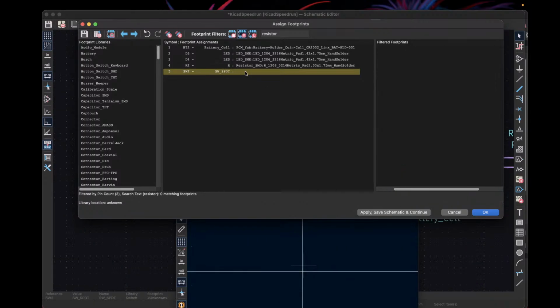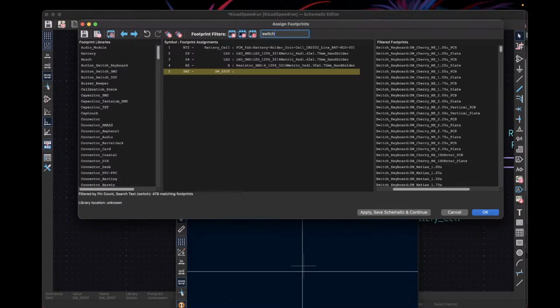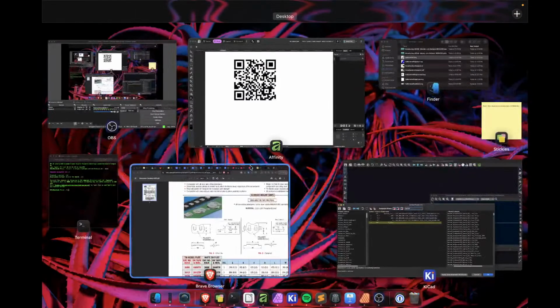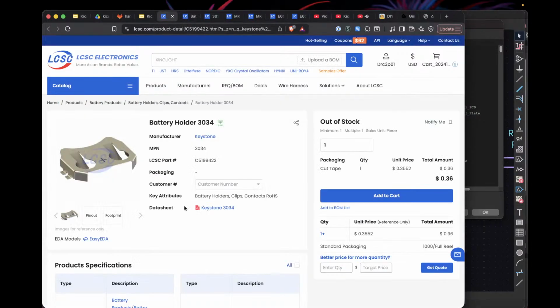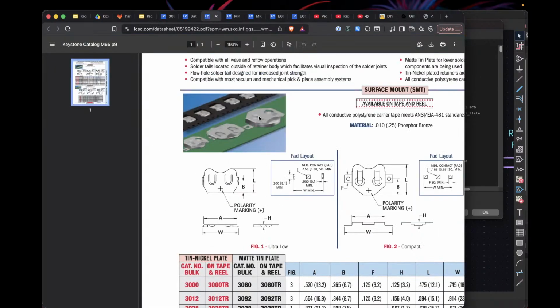Double click on that. Does the software validate correctness? Like if you pick a resistor that's way too big, does it flag it? It doesn't validate anything. You can do whatever you want, basically. You can give it any footprint that you want. Okay. So you will want to double check it later on, typically by looking at the data sheet for the part. For every single part that you find, it's going to have a data sheet attached to it that will tell you all the dimensions for it.